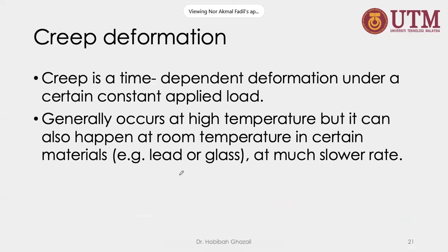So you can calculate 1/3 of the melting temperature for the tin in Kelvin, then convert back to degrees Celsius. You may obtain about 20 or 30 degrees Celsius. At room temperature, it may induce the creep behavior.